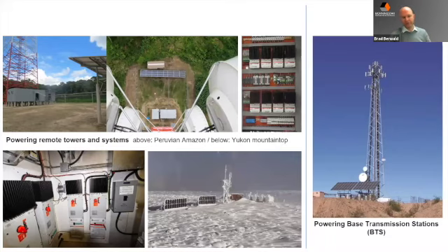And you can see how far north it is because of the vertical nature of the orientation of the solar array. So here's an instance where making sure that your voltage is correct, accounting for that voltage drop or minimizing it with high voltage, is a pretty critical application.